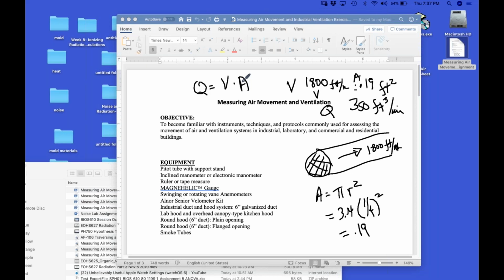Okay. Now hold it exactly 3 inches right up front. You don't want to hold it right against it. You can use the ruler for this one. Hold it exactly 3 inches from the front of the hood, right in the middle. Now the only trouble is that you've got to take your other hand away. Okay, good. What are we reading? 3 inches, 266 feet per minute. Okay, good. Write that down. 266.